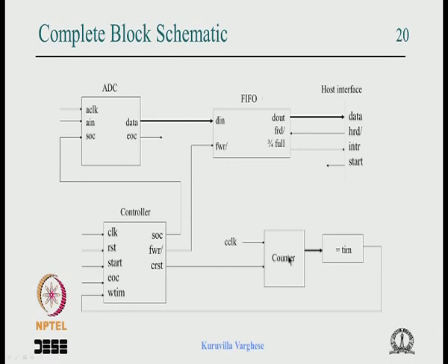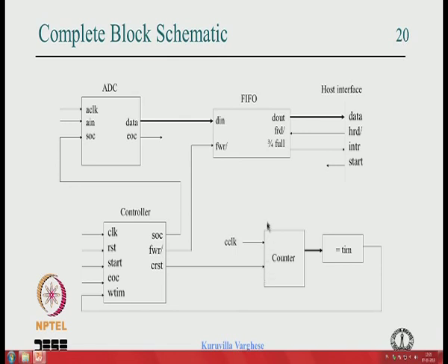So we added a subsystem now. The next step is that we have to update the timing diagram, which is very important. Most people hate this kind of systematic approach. They think it is very pedantic to draw, but if you don't draw, you can make mistakes. In a complex design where multiple teams are working on a project, small things can make a difference, and when you integrate everything, you find some silly mistakes cropping up.